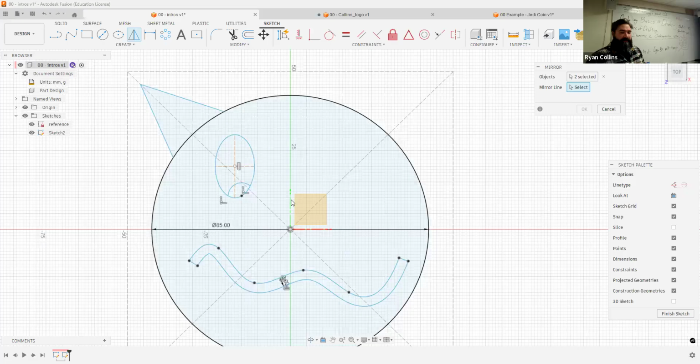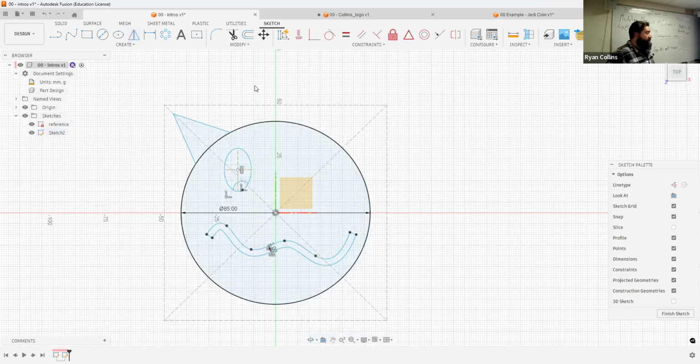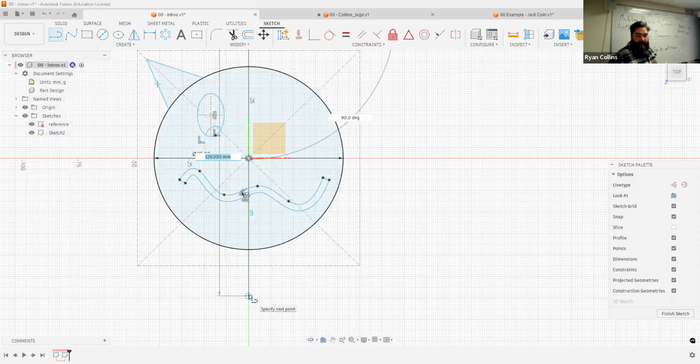Now, technically, you might be able to select the axis line. So I'm going to hit cancel, and what I need is a line straight up and down the middle. So I'll go back and use the line tool. Somewhere above, but make sure it's right on the y-axis, the green line, and then somewhere below. Does not matter. I'm going to hit enter.